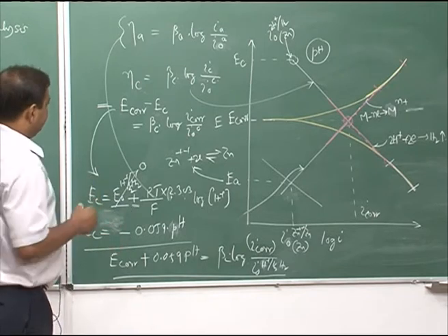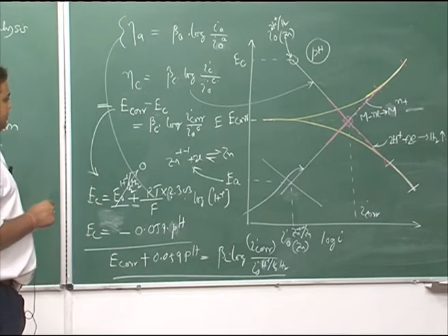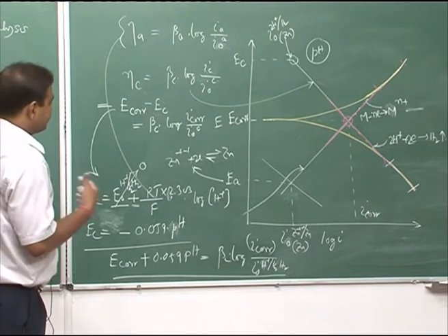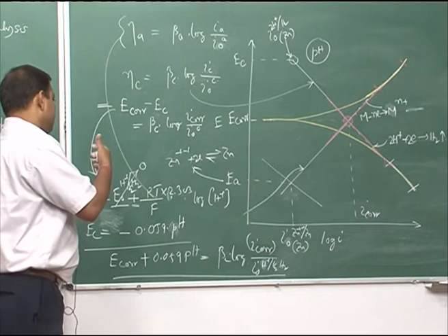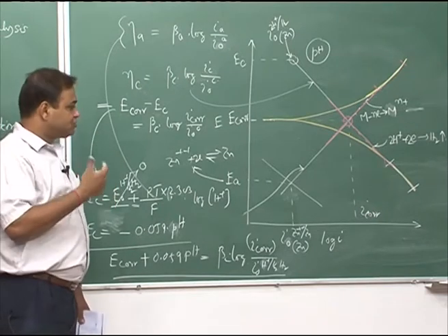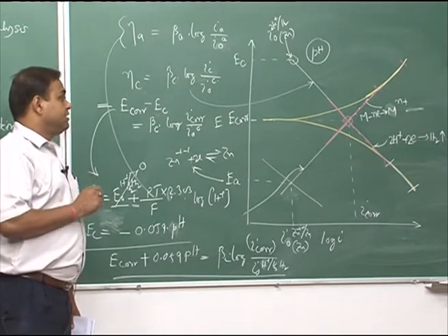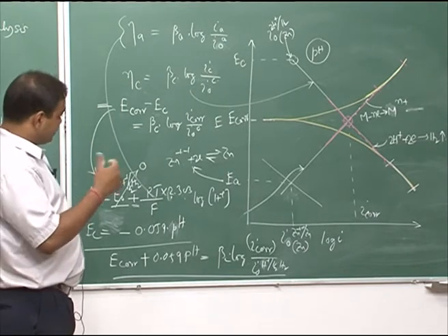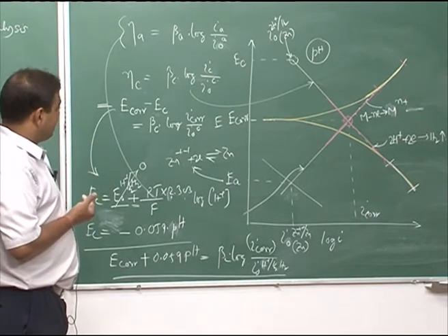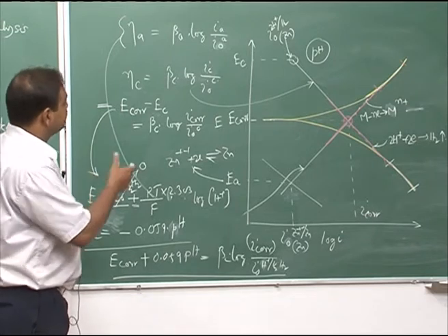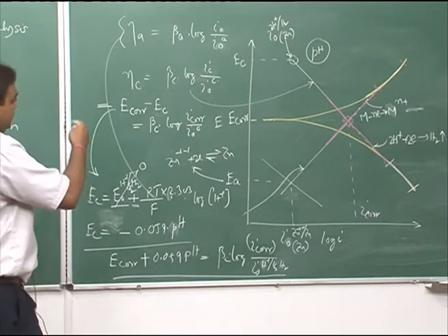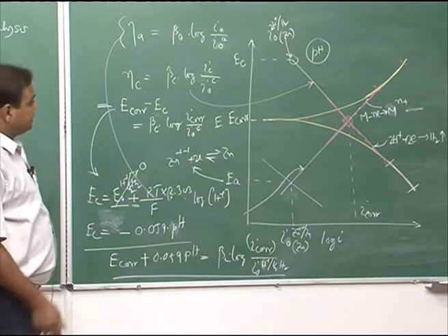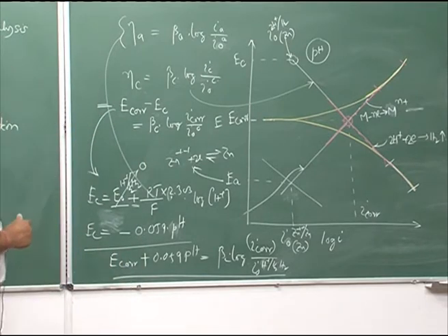And this is a relatively quick method compared to the plant exposure, but it does not give the actual response of the material in actual application. But it is advantageous because immediately it can give you an initial idea about the corrosion rate of that metal in that particular solution.